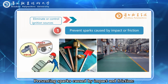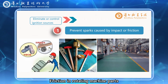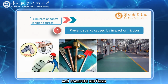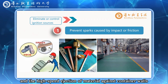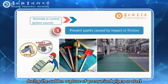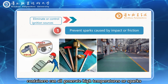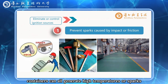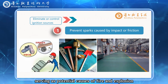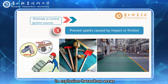First, preventing sparks caused by impact and friction. Friction in rotating machine parts, collisions between steel objects or between steel and concrete surfaces, and the high-speed ejection of material against container walls during the sudden rupture of pressurized pipes or steel containers can all generate high temperatures or sparks, serving as potential causes of fire and explosion. Appropriate measures must be taken in explosion hazardous areas.